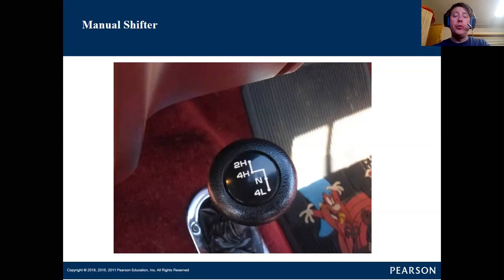You have to pay attention to how that transfer case is lubricated, because if it needs the input to spin in order to splash lubricate and/or run a hydraulic pump, you have to be mindful of that, because you cannot flat tow that vehicle if it needs the input of the transfer case to spin in order to lubricate itself.